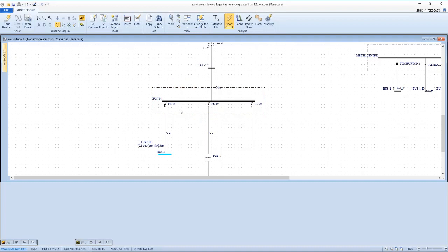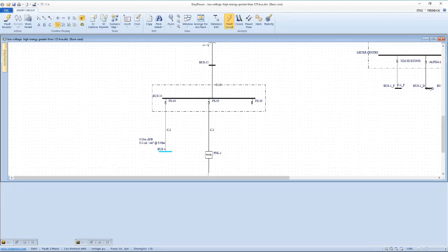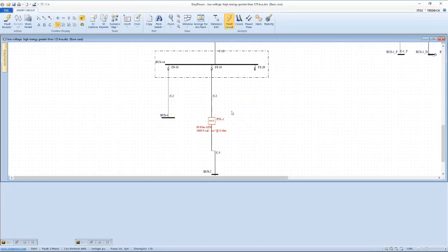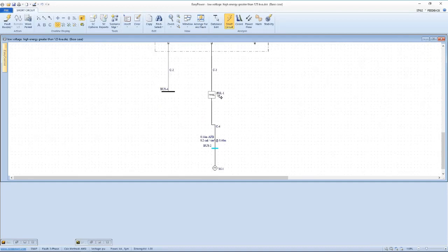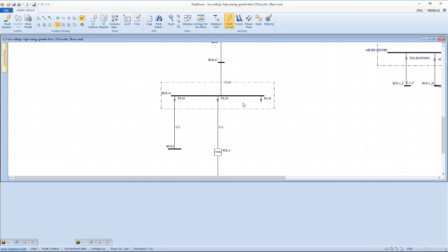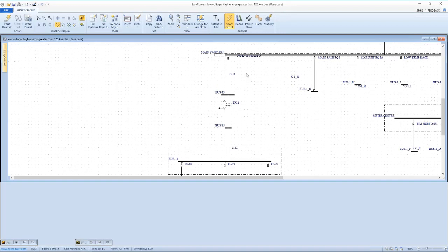If we look at an individual load fed from one of these lower voltage fuses, we see we have reasonable energy down here, and the reason that one's so high is I'm not sure, because I haven't finished populating it. But the point is, on the 208 volt side, as long as I have my fuses on the secondary side, they can be properly scaled for these loads. So the real solution has nothing to do with limiting time. It has to do with recommending a secondary protection scheme that includes the loads in the 208 volt system.